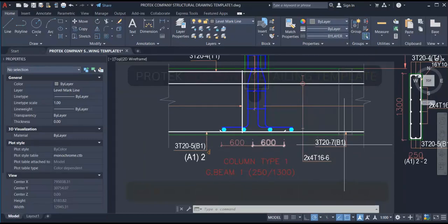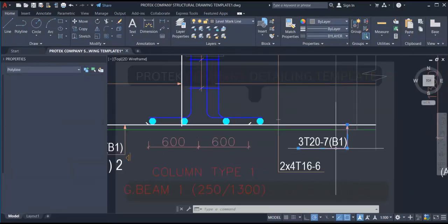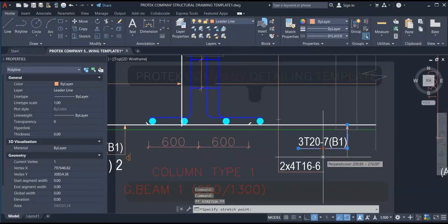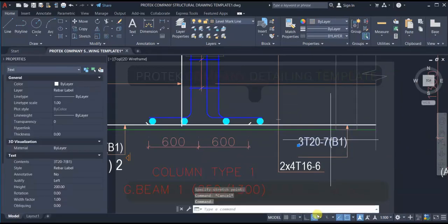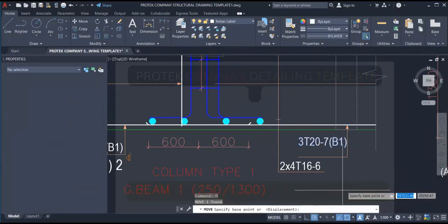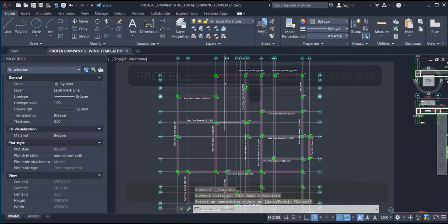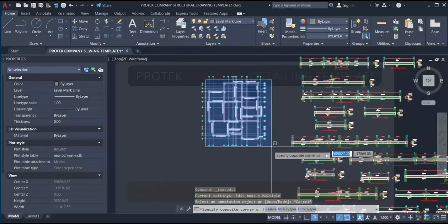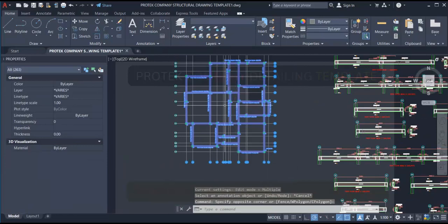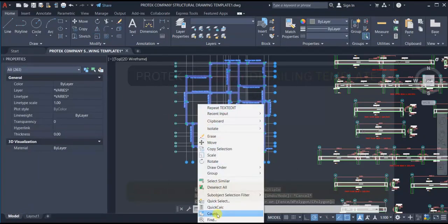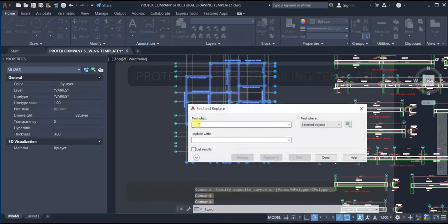We will be providing a kind of a blinding, a blinding of thickness 100. So for us to do that effectively, we may want to shift this downward, and then as well move the text, this go downward a little. Now highlight just like this, so you can have provisions for columns. After which I will right click offset, navigate to find. So in this provision I will offset a blinding thickness of what I have copied.